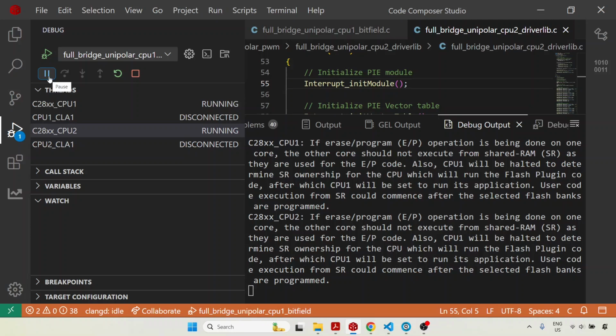I just found this to be the most convenient, because in this case you don't have to keep changing your action qualifier control registers, and this also opens up the possibility of another algorithm where you might want to switch S1 and S2 operating at higher frequencies and S3 and S4 operating at 50 Hz every now and then. This will even out the switching stresses among all the power modules, because at the moment most of the switching losses are occurring in S3 and S4, while S1 and S2 have very low switching losses.